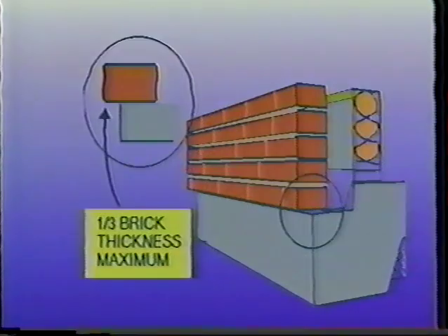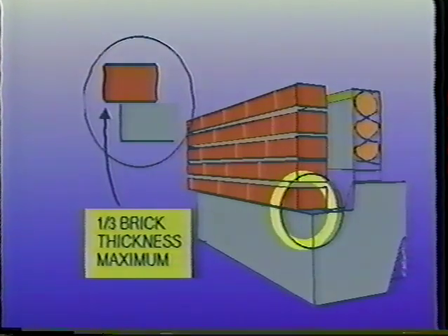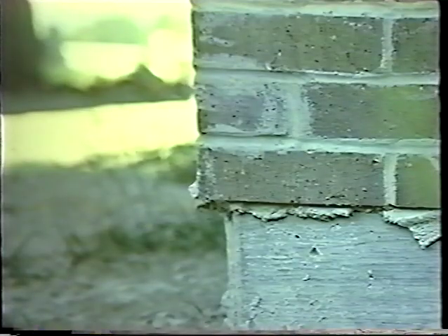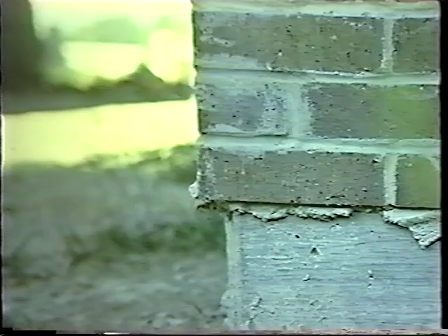At least 2/3 of the thickness of the brick withe must bear on its support. If it overhangs the support more than this, the wall may rotate and crack. Masonry or concrete foundations should be made wide enough to allow proper support of the brick. For a 4-inch nominal brick, there should be at least a 2½ inch support for the brick veneer.